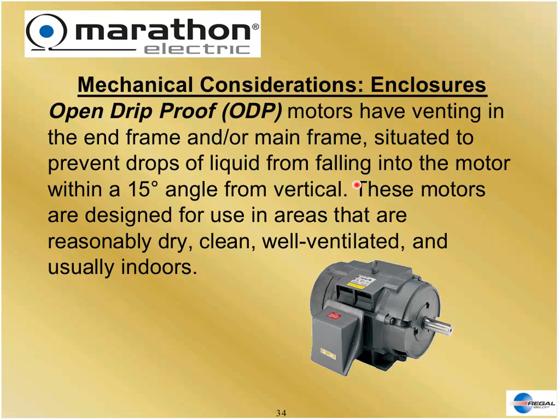So an open drip-proof motor is the most common open motor on the marketplace. It derives its name from the fact that the ventilation openings are so constructed that drops of water or particles cannot enter the motor if they're dropped from 15 degrees on either side of vertical. That's why it's called drip-proof. If the vent holes were all the way around the motor, then it would have to be called simply open. It could not be called drip-proof.